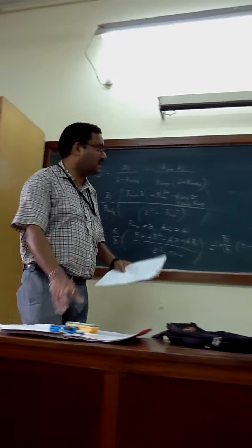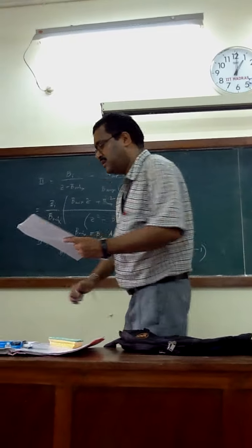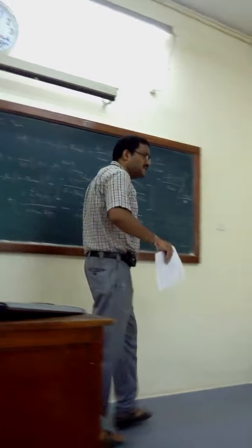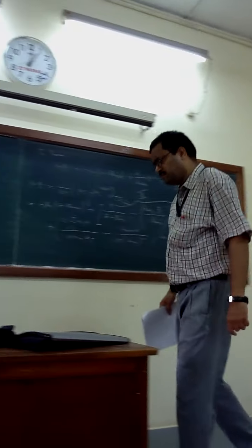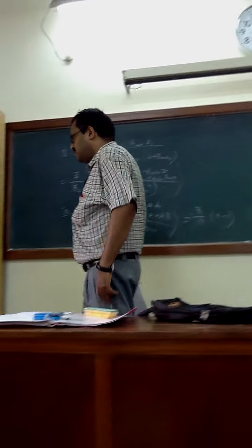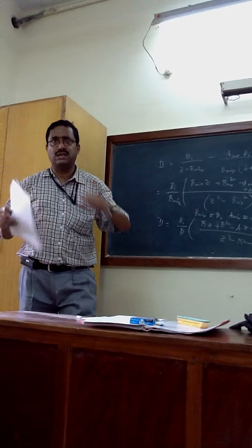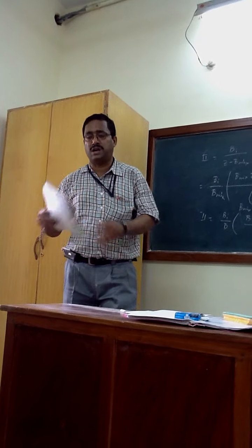Okay, we are doing SRK, the Soave-Redlich-Kwong equation. I will take only this much board space. For the Soave-Redlich-Kwong equation, what is the Z cubic polynomial? Do you have the table with you? Long back I have given the cubic polynomial in terms of Z, one table with the coefficients. Z cube plus alpha Z square plus beta Z plus gamma equals 0. Where are alpha, beta, gamma?